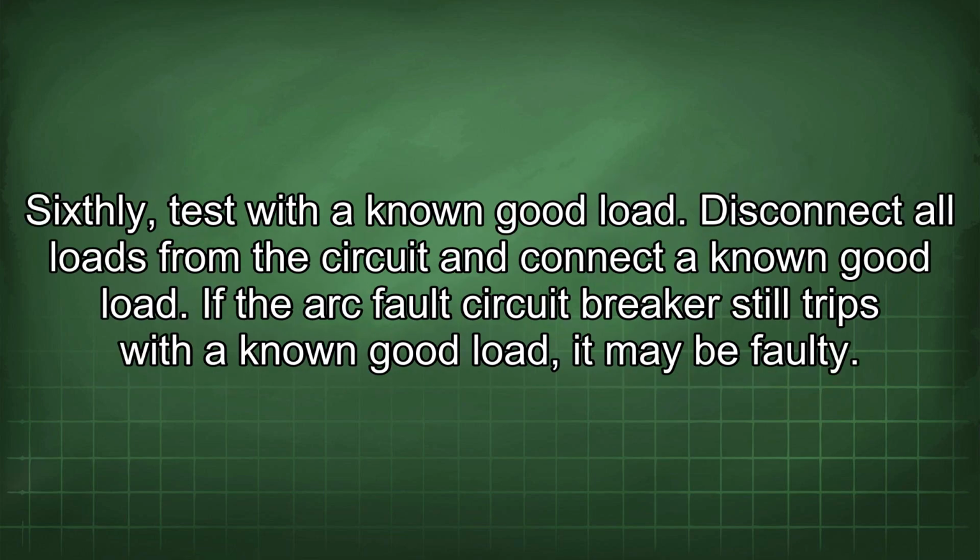Sixthly, test with a known good load. Disconnect all loads from the circuit and connect a known good load. If the arc fault circuit breaker still trips with a known good load, it may be faulty.